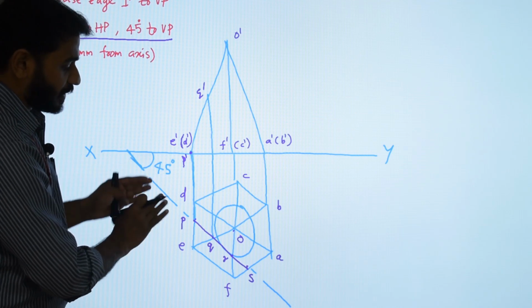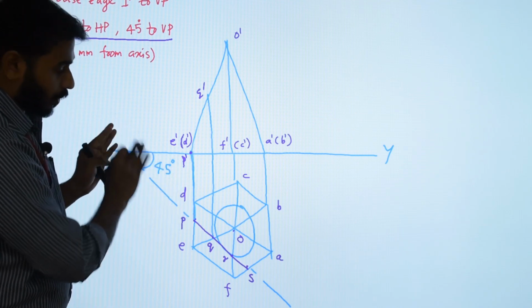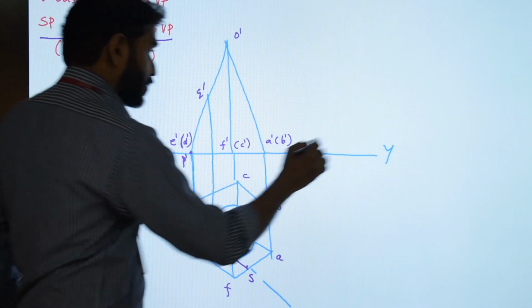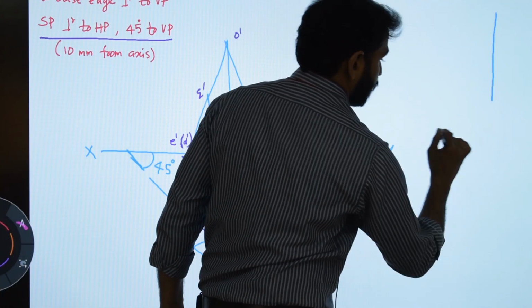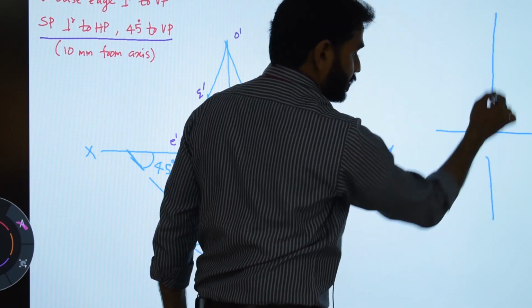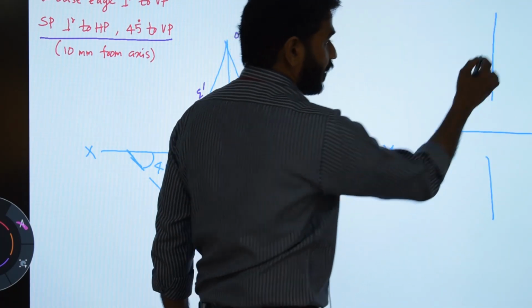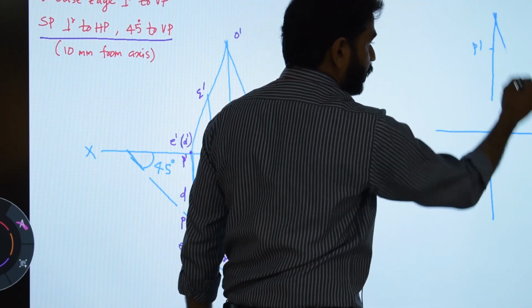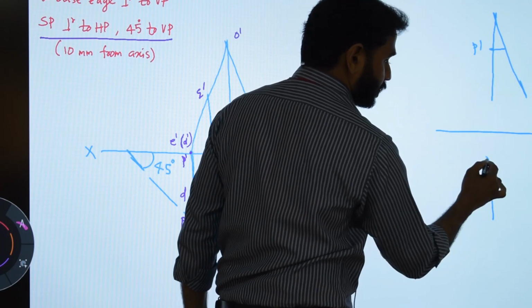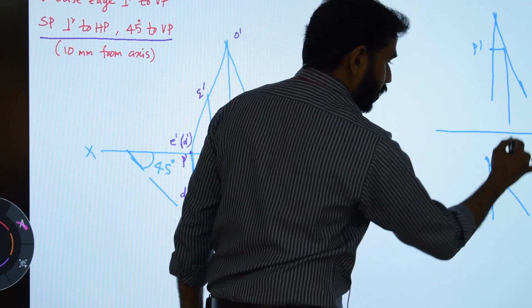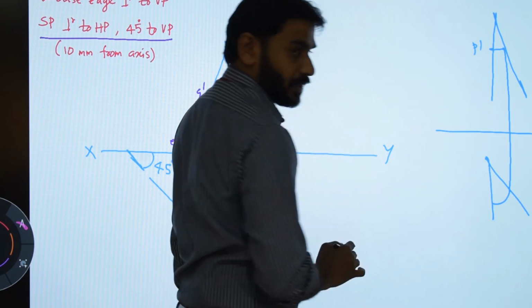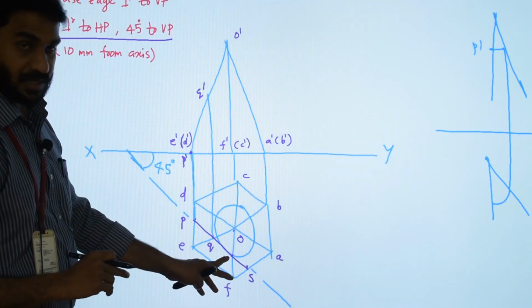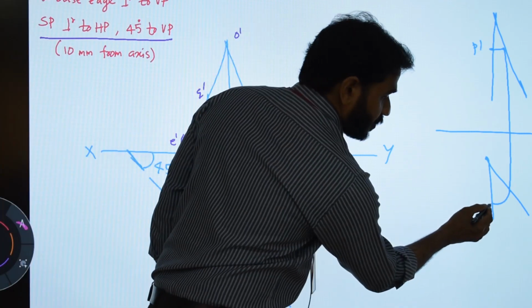So in such cases we will be facing a problem point just as in the previous problem. So here we will be doing the reverse. In the previous question, we had the front view and the top view, both perpendicular to the XY line, and we had a cut point, say P dash. We assumed that we transfer this cut point onto a known position and draw a projector, then rotate. We have to do the reverse here, because here the known cut point is in the top view, which is R. So we have to start from here.